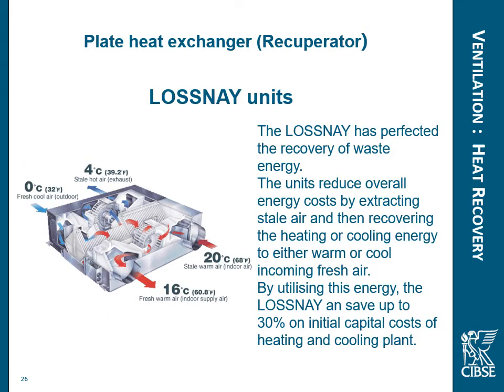So the Mitsubishi equivalent of those is called a Losnay unit. If they were Daikin, they'd be called VAM units. And we can see the heat exchanger cartridge sits inside and quite often has filter medium attached to it. The filter cartridge needs to be taken out to be cleaned.